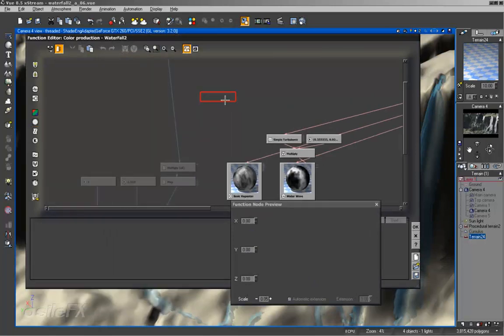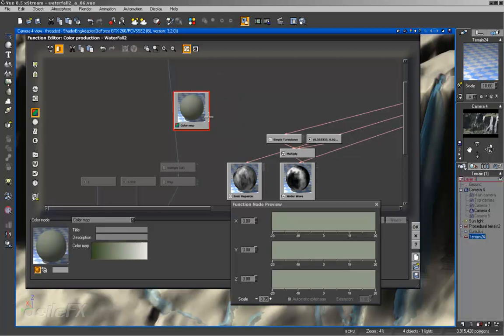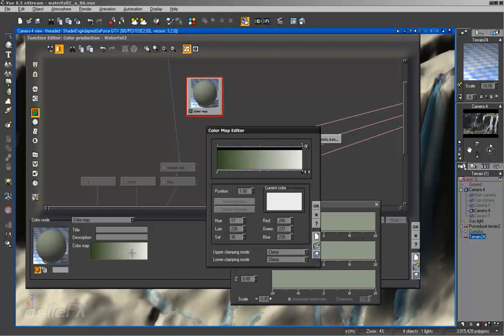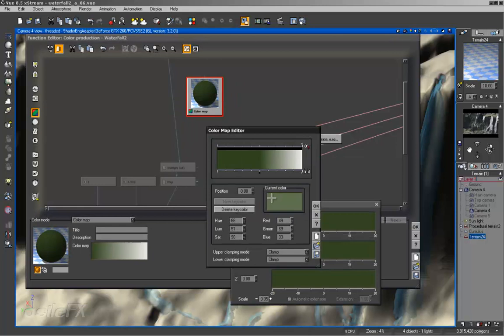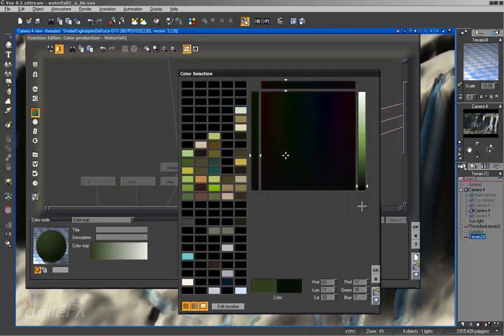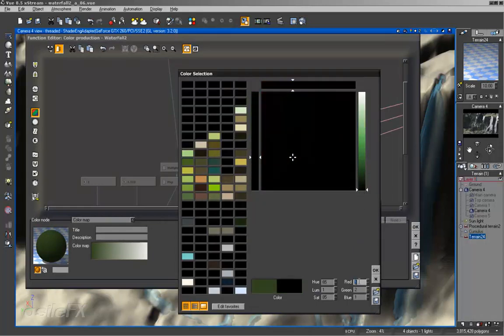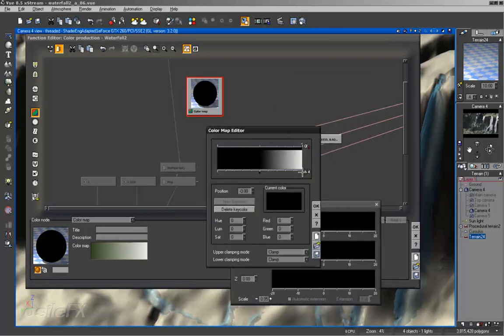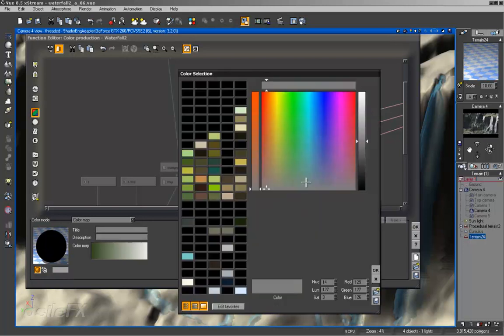now go back into our function, and use our slope controller map, so we can add in color map, edit the color map, we're going to do RGB values 0, 0, 0, and then this is going to be at position 0.75, and then I'm also going to have a much sharper cutoff, so we can create another key point, making it fully white.